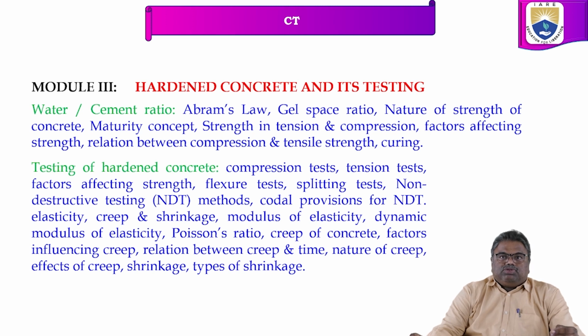In the previous ones, the compression test and tensile tests are destructive tests. We'll cast the specimens specified in the IS code, keep the specimen in the compression testing machine, and apply the load gradually, and we'll see how much strength the concrete can bear. So these are destructive tests. The rebound hammer and ultrasonic pulse velocity tests are both non-destructive tests. We won't disturb the sample, we'll just observe the values. So these two are non-destructive testing methods of concrete.